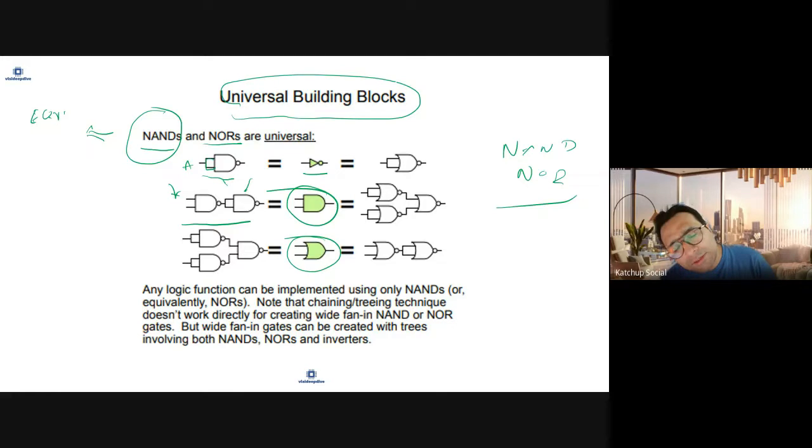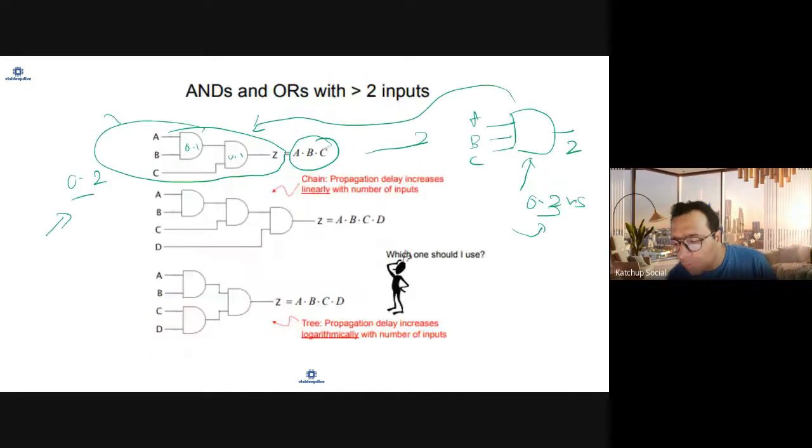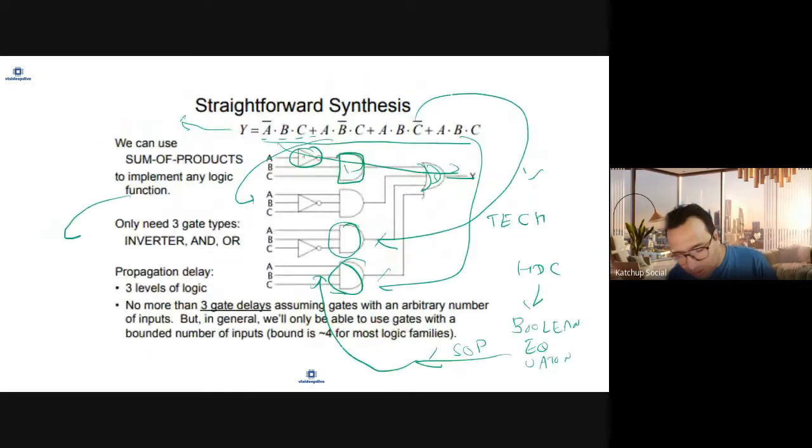And typically the size or the amount of cells, when a synthesis tool represents it, is written in NAND gate cells. So you may hear people say, okay, my design is equivalent to, let's say, 100K NAND gates. That is because NAND gates are universal. With NAND and NOR gates, you can implement any functionality using those cells. Okay. So it has created some Boolean representation of the design.